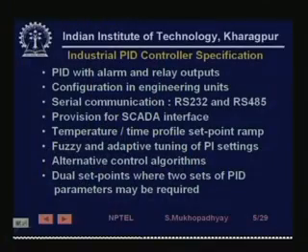Then sometimes you may require two different sets of PID parameters, so you need to give dual set points. On the same process you could use two different PID parameters, maybe depending on two different modes. For example, suppose there are heat-cool PID controllers. Sometimes the same device has to heat, let us take a heating, ventilation, air conditioning, HVAC application.